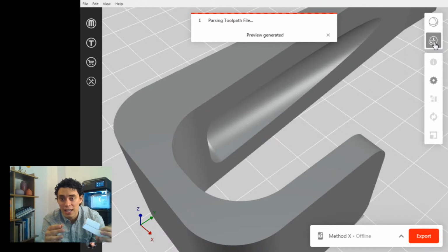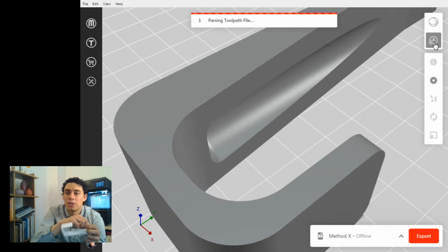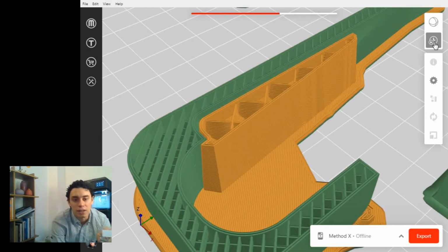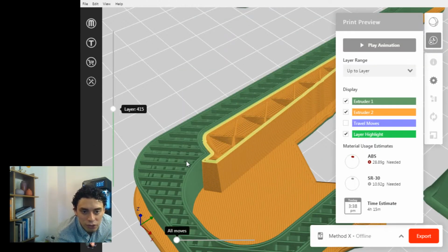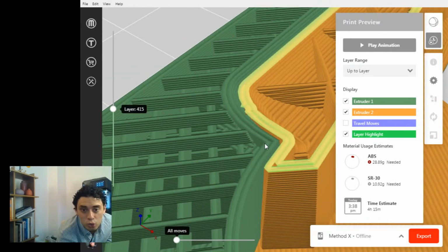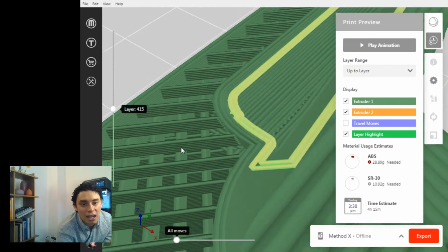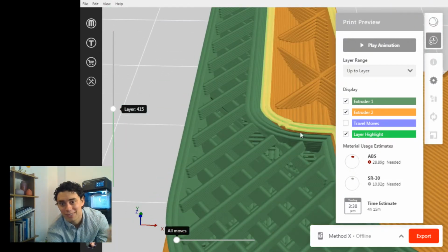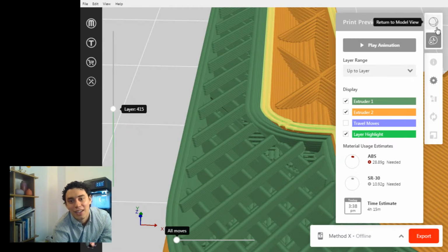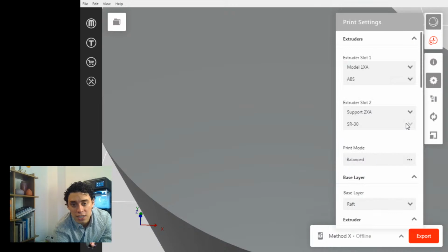Our default, our standard, is 2 shells. That basically means 2 solid walls of material enclosing the infill. And you can already see it here, right? I'll zoom in so you guys can see it. These are my shells, the 2 shells that I'm using. This is the infill, that crisscrossing path. And on the other side, you have the other shell, the other end of the egg, let's say.